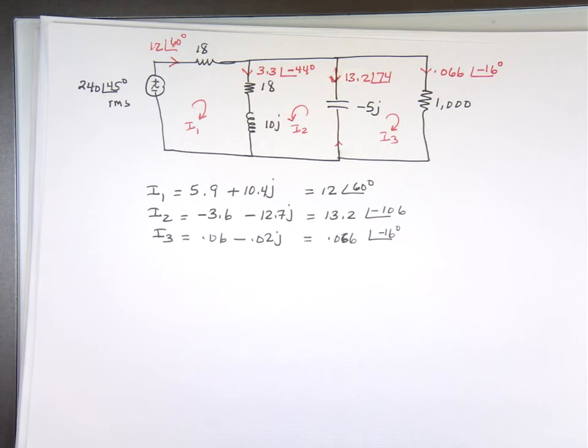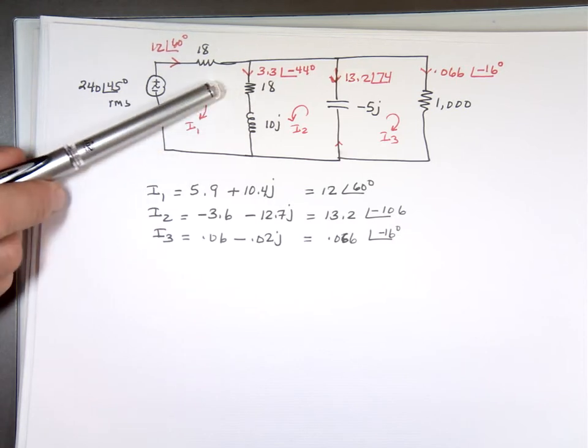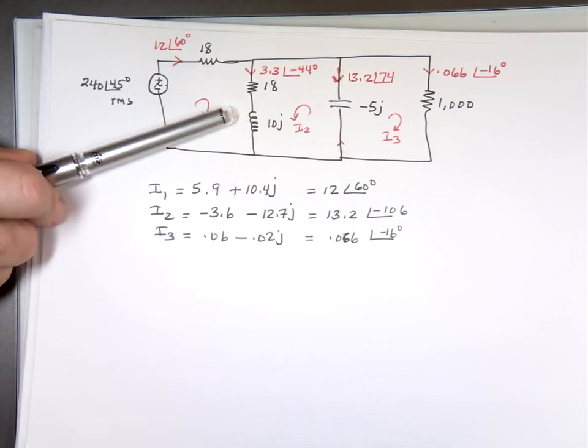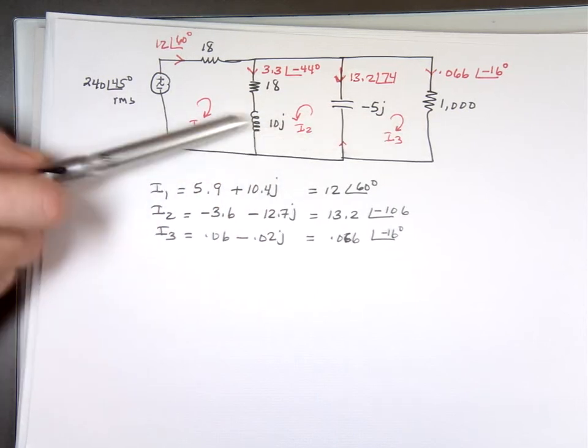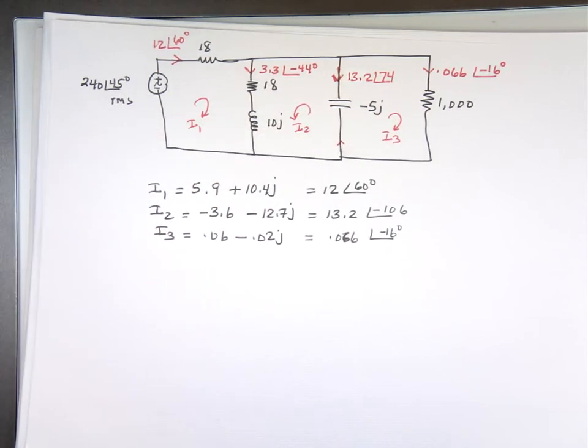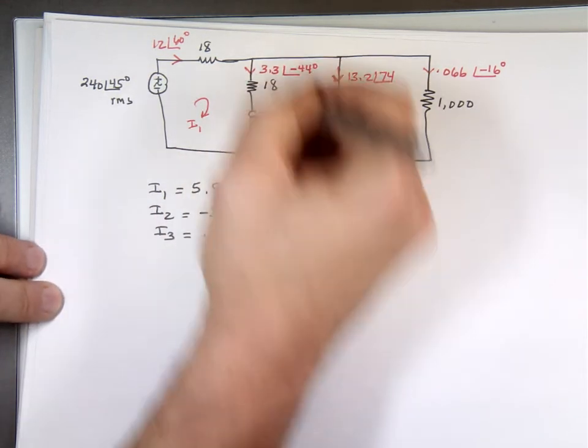What are you trying to find? To find the complex power is V times I conjugate, right? Well, I don't want to find the voltage. I can, but I don't have to find it. You can do I effective squared times Z. The magnitude of that, right? Yep. The absolute value of that, which is the magnitude. So you can find the complex power by this one.